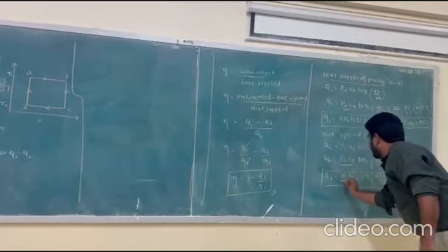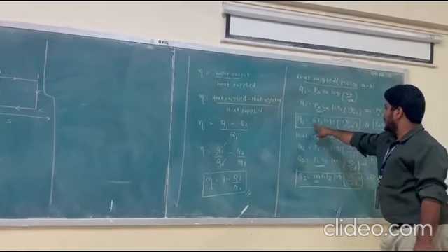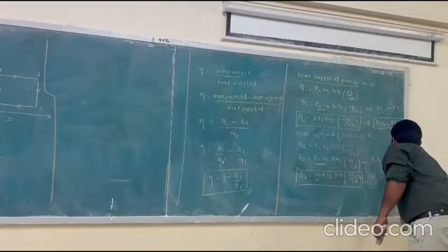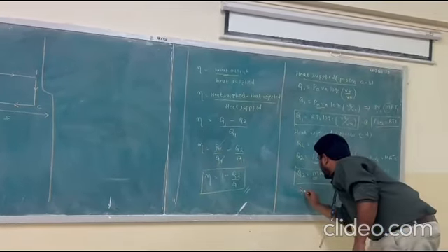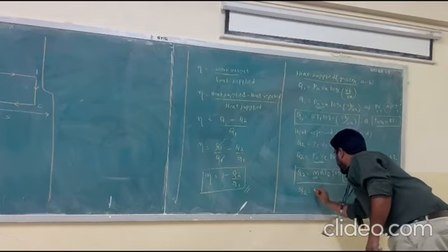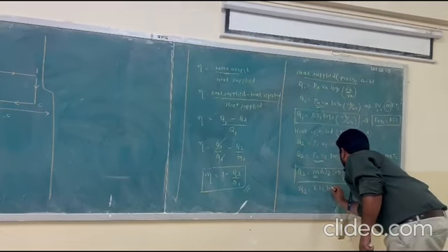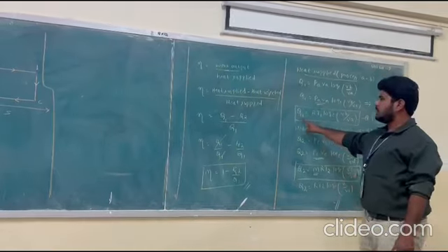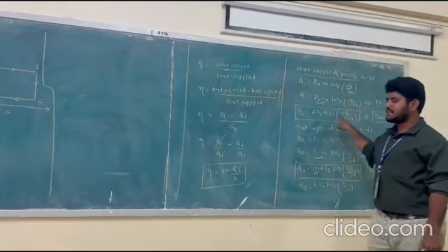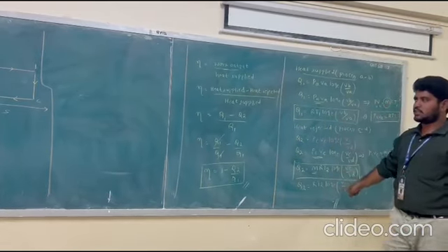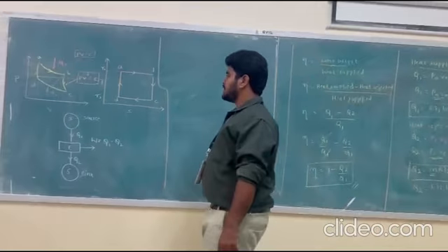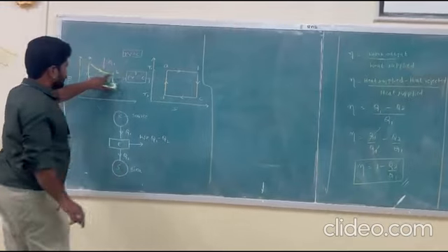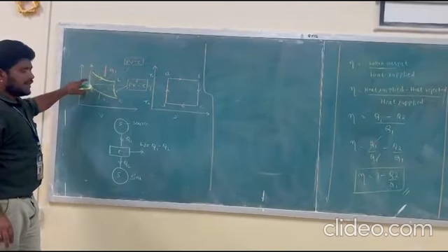Now here I told that in the equation 1 I have to take the mass as 1, m is equal to 1 kg per unit. So I can take Q2 is equal to RT2 log e of VC by VD. Now we have determined the value of Q1, that is the heat supplied, and Q2 is the heat rejection. Now we will go to the other processes, the B to C process and the D to A process.